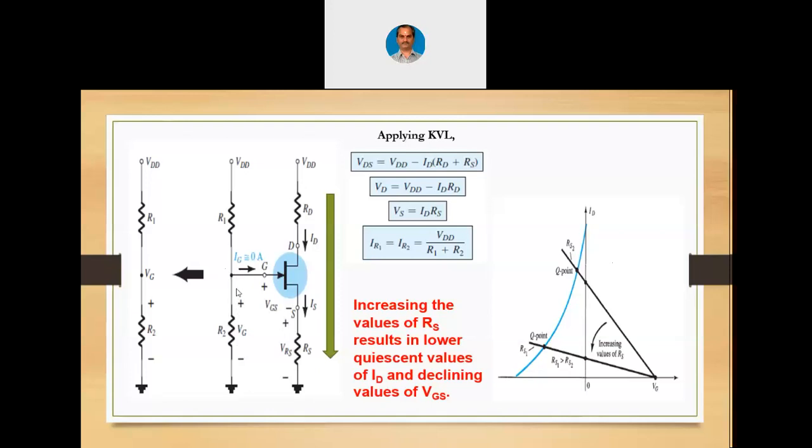Now, okay, I'll annotate and give you a real example. Let us say Vg is now 2 volts. Imagine this way. Vg is 2 volts, and let us say Vs is now 1 volt. Then Vgs is going to be 1 volt, because the total voltage here is 2 volts: 1 volt across this, 1 volt across this.